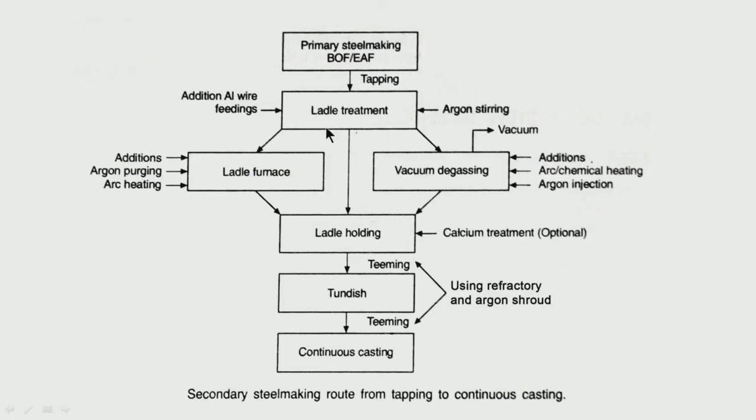First, desulfurization is not possible to the desirable extent, degassing obviously not possible. Too much addition will bring down the temperature. What we can do is deoxidation, and we can do argon rinsing. This is possible. So oxide cleanliness we can control, but sulfur is difficult to control only at this stage. So sulfur control, that means desulfurization, is definitely possible in the ladle furnace.